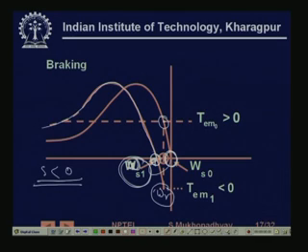So the torque that it will have is now negative. So you see that the electromechanical torque developed has reversed. So the machine is going to slow down and it will try to feed back power to the source. So you see that by changing this frequency we can also achieve braking, right.